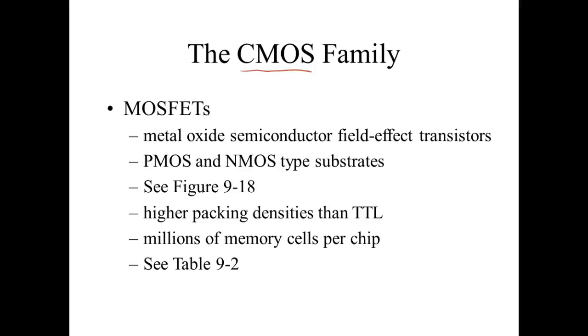The problem we have with MOS is that the coating, the insulator that's between the lead that we call the gate, is an extremely thin insulator. And we have a tendency to build up charges. And if you touch that thing and you pop it or discharge through that CMOS, you could rupture the insulator that's between the gate and the other two leads. So MOS circuits are susceptible to damage with static electricity. So you got to be real careful when you're handling the memory of your computer or your processor or anything inside that computer, because there's a lot of MOS in there.